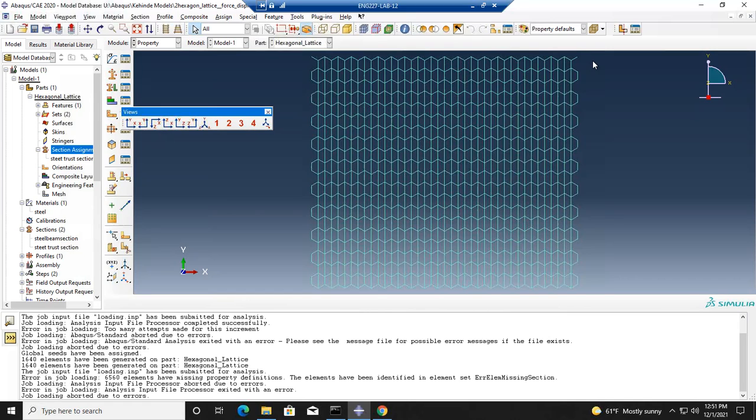Okay, okay. So you see, we don't need to worry about any kind of failure. We don't need to think of buckling or anything like that, because right now we are ignoring all that. We are just thinking everything is linear elastic and we are doing it. The only instabilities we need to worry about right now is joint constraints and restraints. Of course, in a real system, what you're saying, yes, absolutely, that is true. But this is a model, right? So we can give whatever we like here.